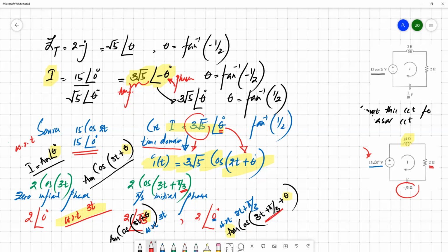If those elements are in series and parallel combination, you can use the very fundamental rules of simplifying series and parallel combinations and find the equivalent impedance in the form of a complex number, a real plus an imaginary component, and then just divide the voltage by that impedance, or if you multiply the impedance with the current, you can get the voltage.